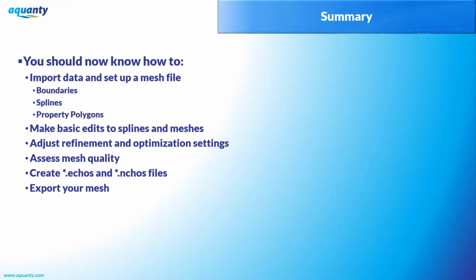Yeah, the only thing you have to be aware of is if you need that streamline in the future as a shapefile or something like that, it wouldn't have all the attribute information from the original data set associated with it anymore. But if that's not necessarily important to you, it's definitely easiest to just do that simplification in AlgoMesh using the resampling and potentially the clean geometry tool.